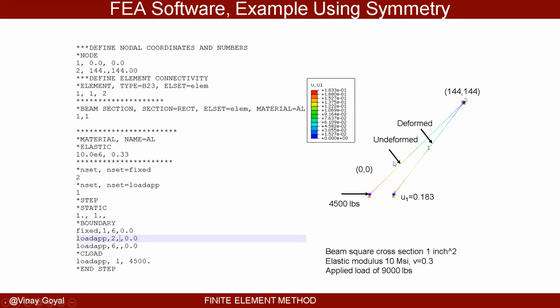Bottom line, this concludes today's lecture, and I hope you enjoyed it. It's very important to use beam elements to simplify finite element models that are very large, because you don't want to be modeling stiffeners and longerons with 3D elements. They're computationally expensive, and so we want to save those elements for something else that can be represented with 3D elements, which is not a lot, to be honest. We showed you that last week.